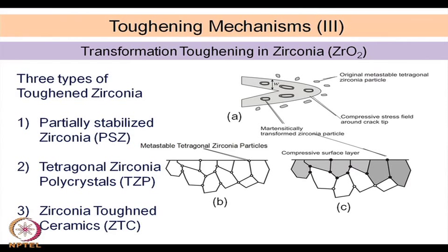So, that can also be prepared by very fine particle size. If a nanometric particle size of zirconia is prepared, the tetragonal phase automatically gets stabilized. In fact, it is a metastable phase of course, but at room temperature it remains almost indefinitely unless you stress it. Okay.